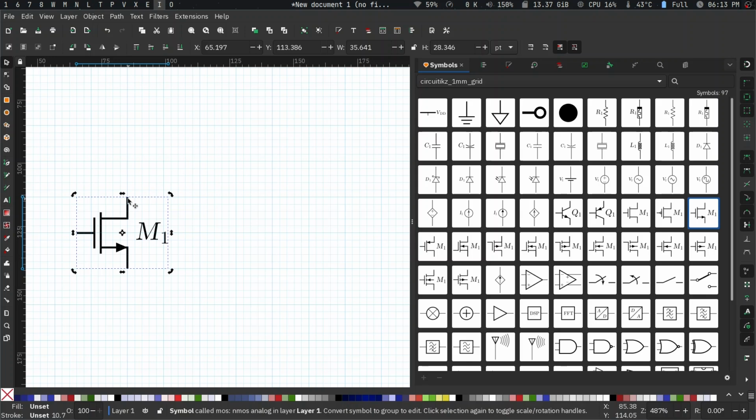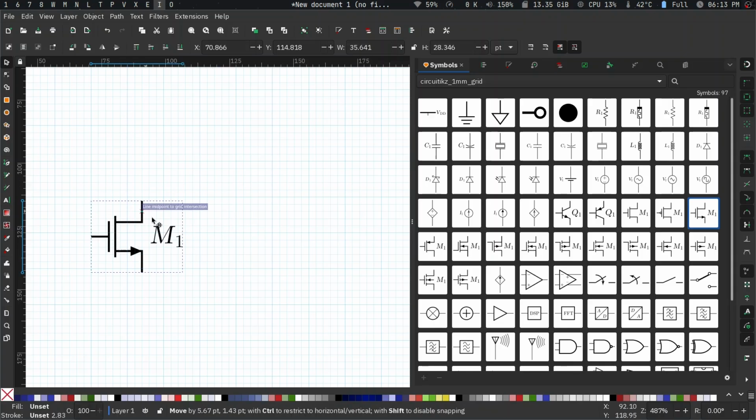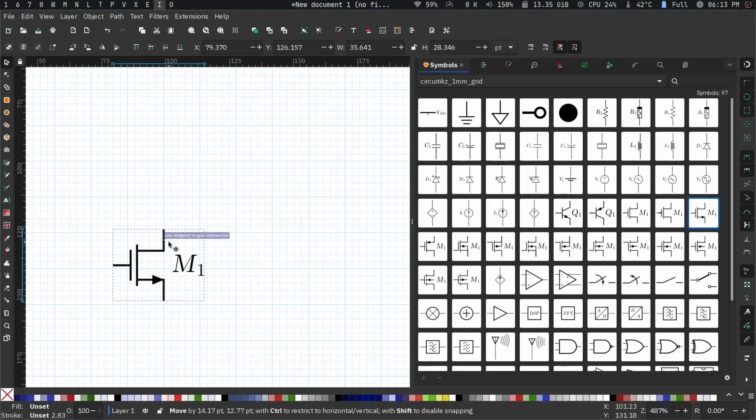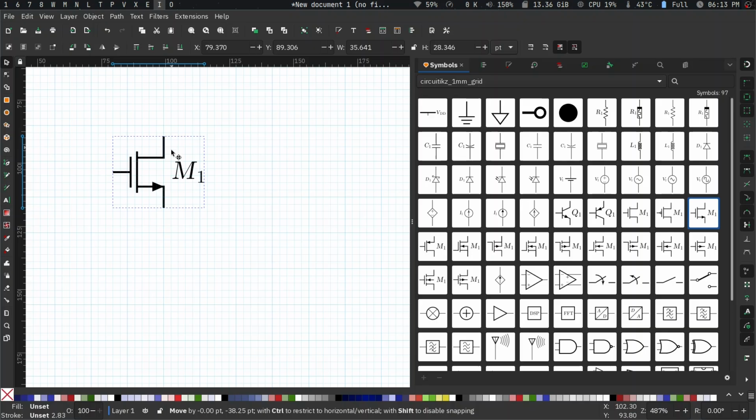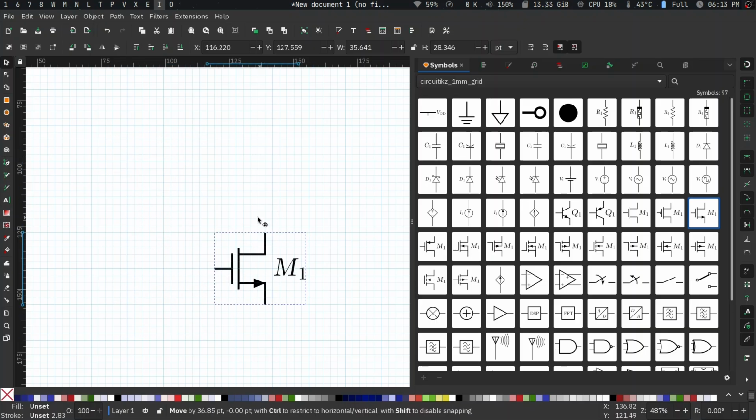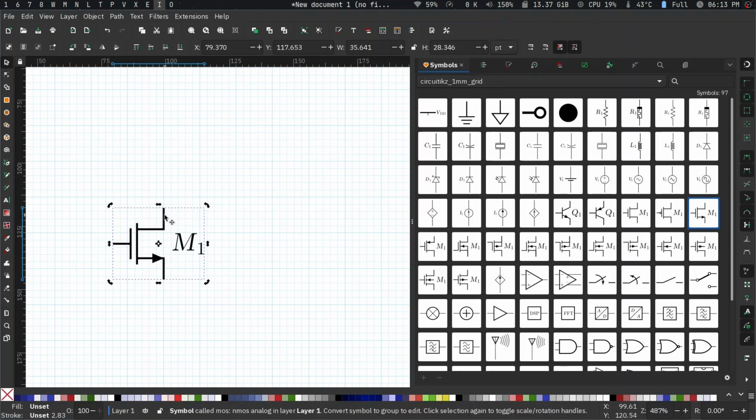Now, if you haven't used Inkscape before, I am going to recommend something. At the moment, all I'm doing is just moving it with the mouse. Because you can move in any direction, sometimes it can be a little hard to snap this guy on the grid exactly. So let's say you want to move your mouse in any crazy way, but you want the motion to only be along the vertical direction. You can always hold Control. When I hold Control, you can see I can move up easily. If you want to go in the other direction, you do it like this. So always hold Control if you want to be more precise in one direction.